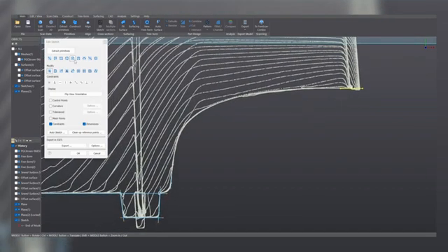Good. Now, to close it, we add a spline. We're gonna use 2 control points and close it with the endpoints of these lines. Now, because we want a smooth transition, let's make them tangents. So select first the spline and then one of the lines and click on the tangency constraint.